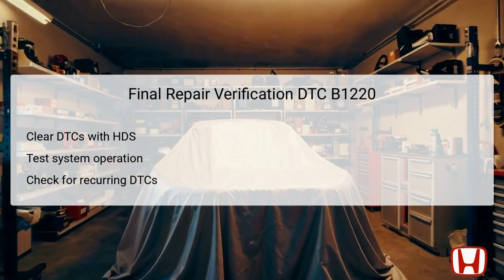This step checks that all components respond adequately when adjustments are made by the user. Lastly, after thorough testing, rescan the vehicle for any recurring DTCs. This verification process is essential to confirm that repairs were effectively executed and that the climate control system is now fully operational without any underlying issues present.